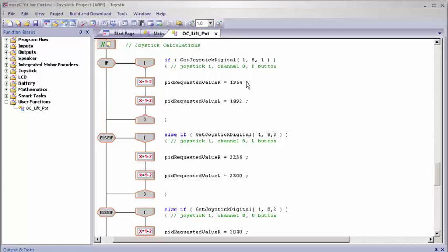What you want to do is calibrate them at their highest point, because that's where you do not want any difference between the sides of your lift. You need to know 100% that there is no difference between the sides of your lift when it is all the way up at its maximum height, because if it is twisting while it's up there, it could flip over to the side, or you could grind some gears, or who knows what else. So you want to calibrate it at the very top.